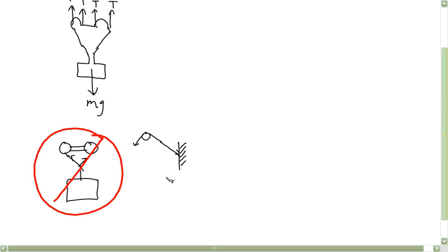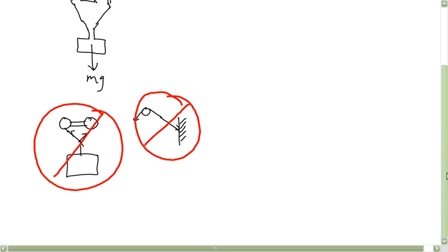I think you'll be surprised how much clearer it is in your own head when you start thinking of all your free body diagrams as like you break off a piece, shrink wrap it, draw the shrink wrap. So that's what I want to see, not this, definitely. So did we need a free body diagram of the wall then? No, you didn't need one, but if you wanted to do a free body diagram of the wall, if you think about it as breaking off a piece and shrink wrapping it, then it becomes clear what you need.